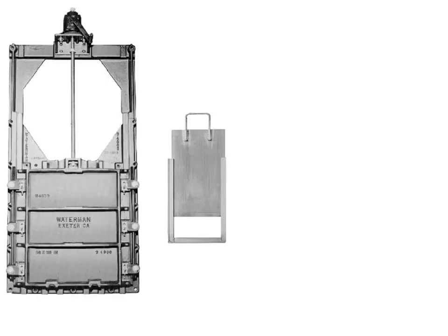You can see that it's basically just a sheet of metal in between a frame, kind of like a window frame, where the water is going to be pressing towards us, and it would be holding the gate up against the surface along the edges. And so not only have you got the weight of the water to lift up when a gate like this is open, but also there's the hydrostatic forces pressing the gate up against the frame. So it would be very difficult to pull that up if there was very deep water.